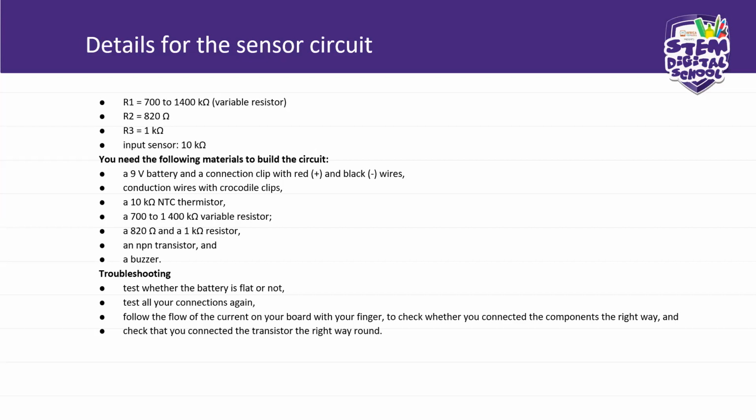Something might be wrong somewhere. Some component might have lost its value. Okay, some components might even have a factory fault. You see, it is made to be a certain value, but practically when you measure it, it's not even that value. So it's best to check the values of the components.